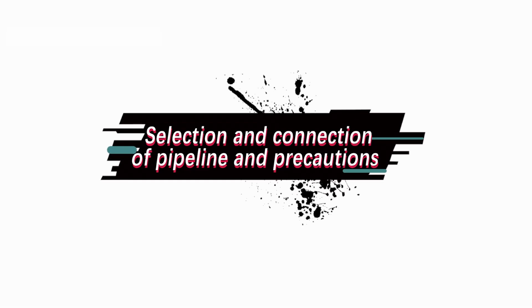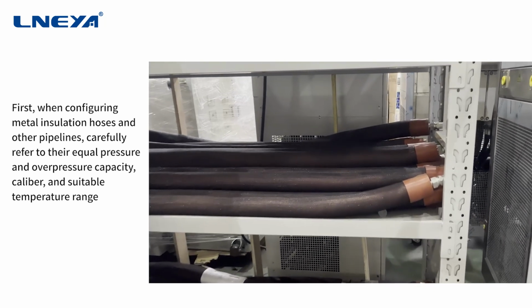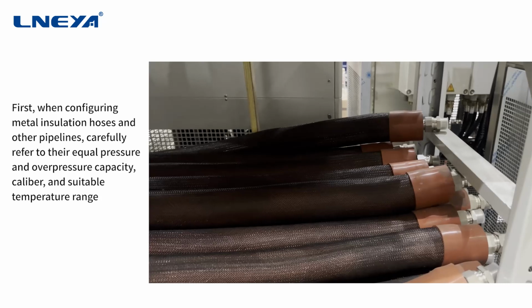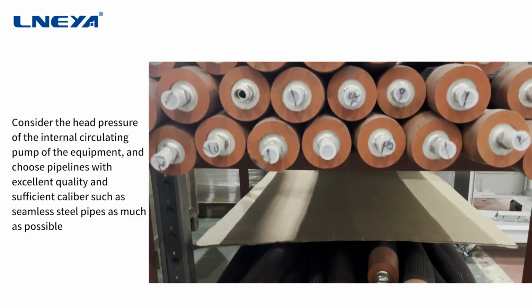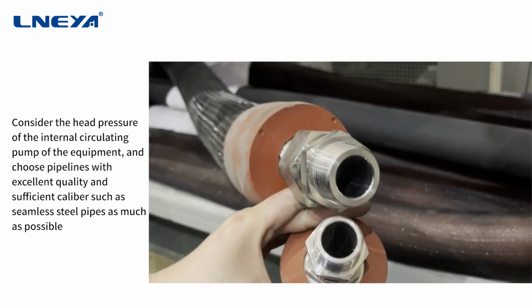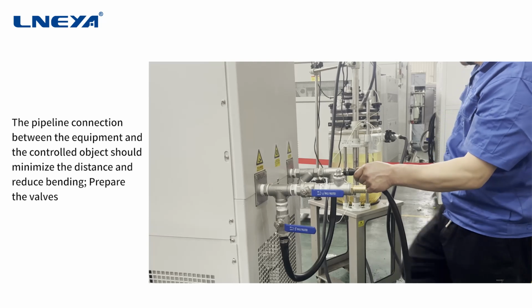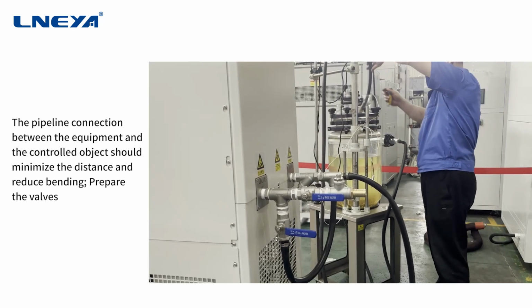Selection and connection of pipeline and precautions. First, when configuring metal insulation hoses and other pipelines, carefully refer to their pressure and overpressure capacity, caliber, and suitable temperature range. Consider the head pressure of the internal circulating pump of the equipment, and choose pipelines with excellent quality and sufficient caliber such as seamless steel pipes as much as possible. The pipeline connection between the equipment and the controlled object should minimize the distance and reduce bending.